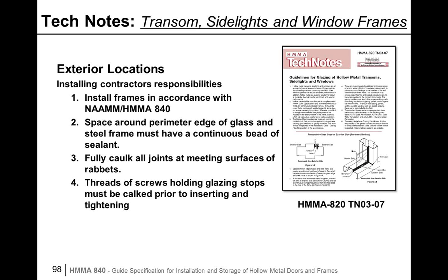There are clear instructions for the contractor on how to caulk the seams properly, how to fill any kind of defects, etc. The caulking of the window lights, whether it's door or frames, is the responsibility of the contractor. So this document helps offset any types of future back charges related to transom side light, borrowed light, leaking from weather.